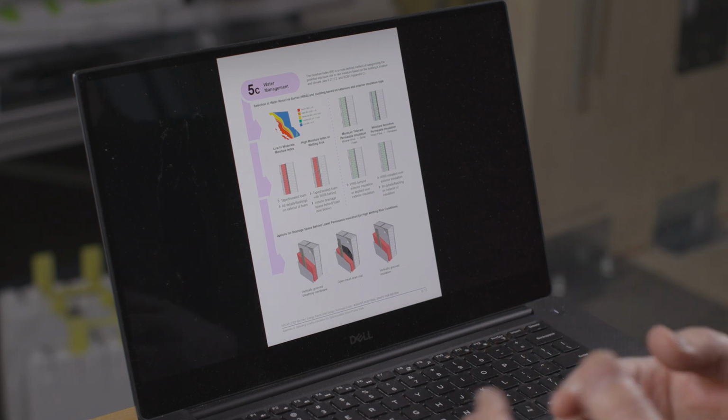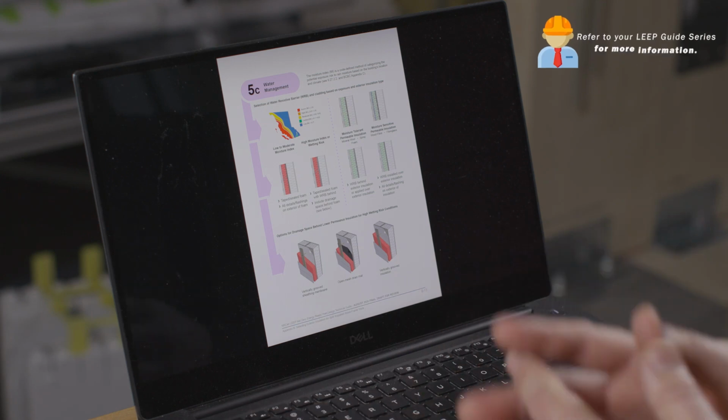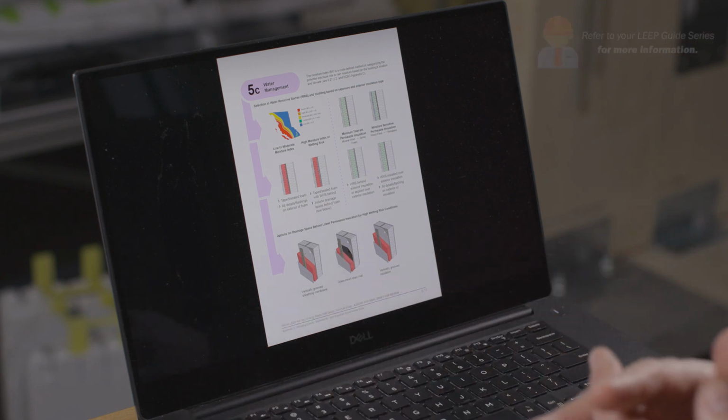If you're in an area with a high moisture index, you need to take a bit more conservative approach with your water management. In code currently, that would be things like rain screen designs and other details for water management and flashings. Versus in low regions, the drier parts of the country, where the risk of water penetration is much lower. And so there are two approaches. And this is where wall 3 and wall 2 get differentiated. Wall 2 is generally recommended for low moisture index regions. Wall 3, with the details that we cover in the guide, is generally recommended for the wetter regions. So you've got the two choices and you can use them.